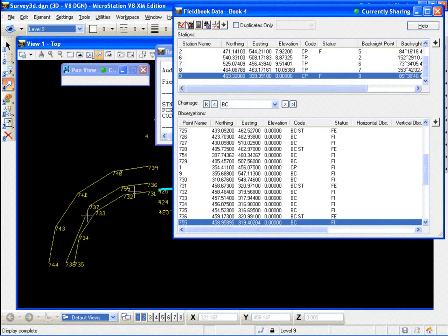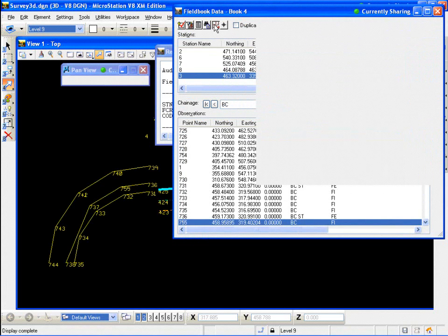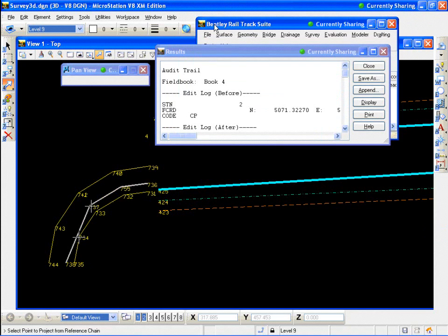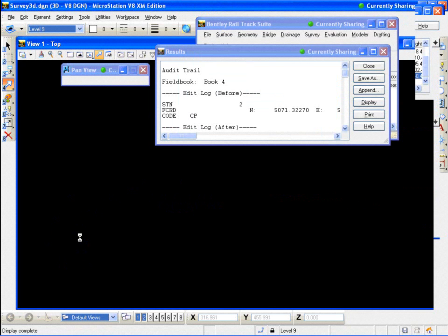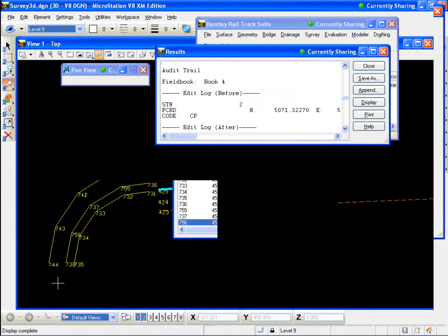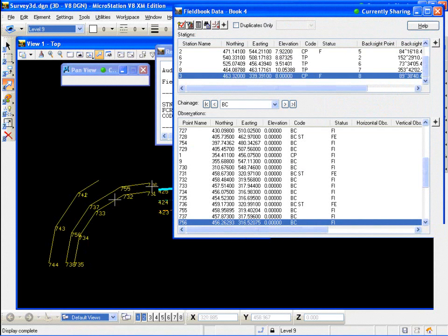I'm going to add one more down here, pick point 733, 737, then project 734 over to that point, and as you see, this line is much more parallel than it was before. And if I added my PCs like we'll do in a minute, these lines will all be curves and parallel. So this is my curve, and this represents my gutter, and they look a lot better now than they did before. Okay, so let's go back to the PowerPoint slide.